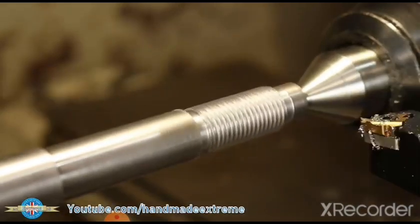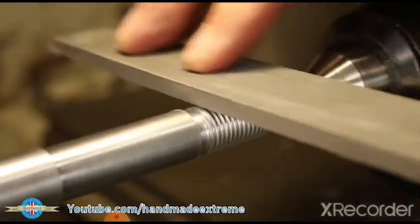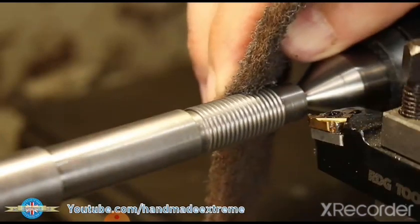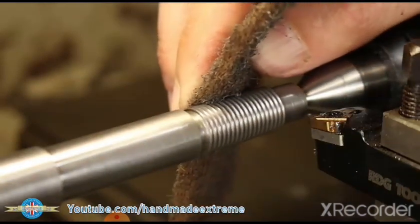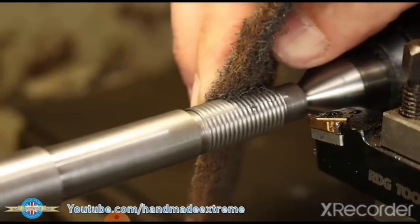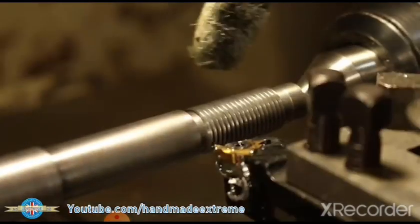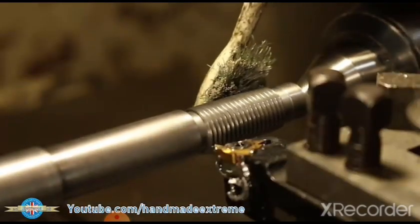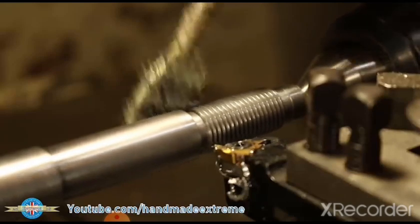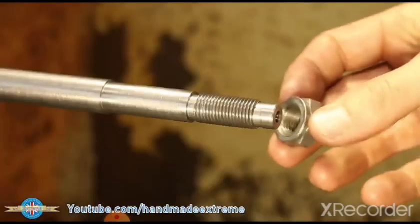Right, just knock the tops off, because I think we're about there. A little bit of emery paper and a bit of Scotch-Brite at the end just helps to clean up the threads, get rid of the tool marks, and you always end up with a few little niggles that you need to get rid of. A small toothbrush or a wire brush is really good for cleaning the little bits of swarf out of the threads before you test fit your nut. There we go, finished thread.